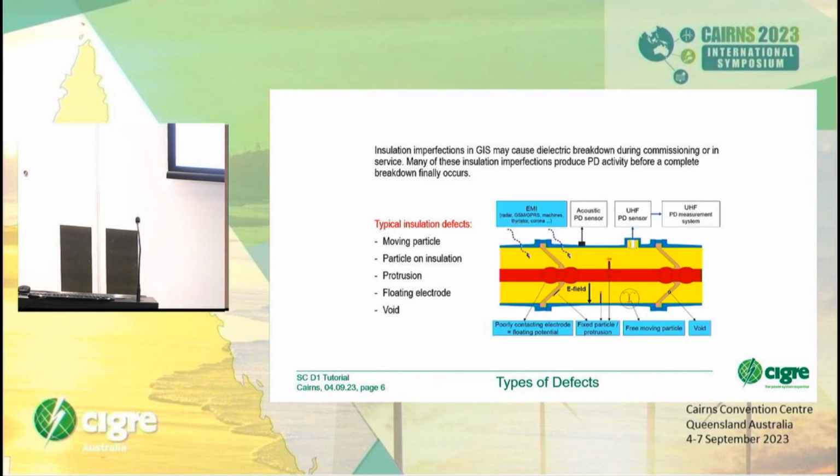With the basics, we have to look into the electrical insulation system of GIS or GIL. In detail, we have a metal-clad, gas-tight enclosing housing, today made of aluminum. This housing is at earth potential. In the middle we have the high voltage conductor with the high voltage on it, and the current is running in this conductor. In yellow, this is the insulating gas, which up to now for gas insulated systems is 99.99% SF6.